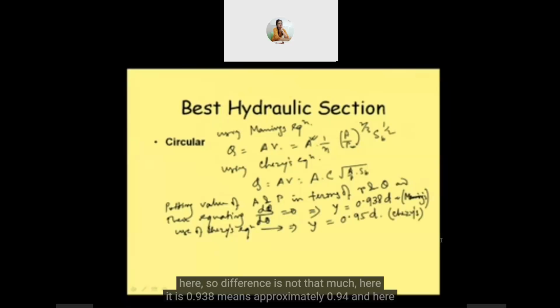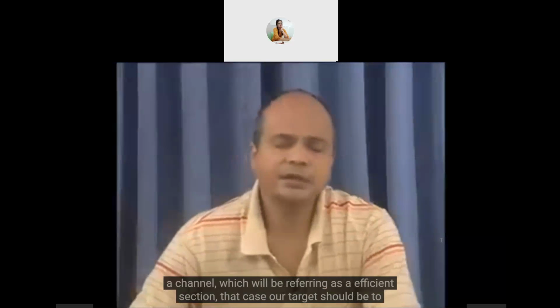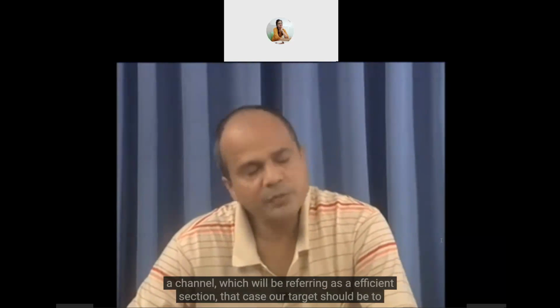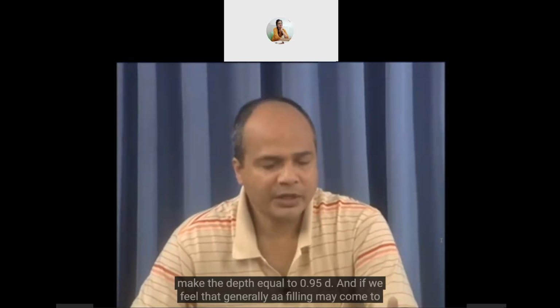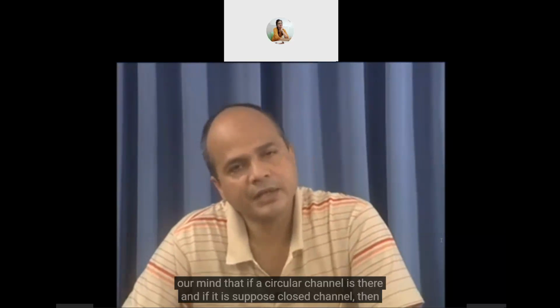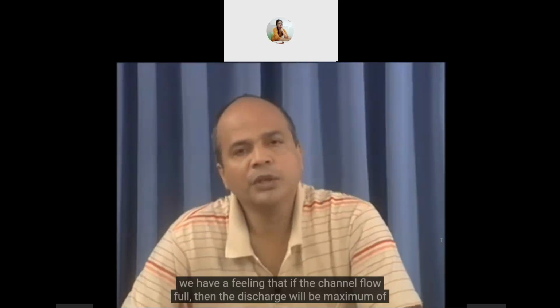Well, here the difference is not that much. Here it is 0.938, which means approximately 0.94, and here it is 0.95. So if we want to have maximum discharge through a channel, which we will be referring to as an efficient section, then our target should be to make the depth equal to 0.95 d. A feeling may come to our mind that if a circular channel is closed, then if the channel flows full, the discharge will be maximum.